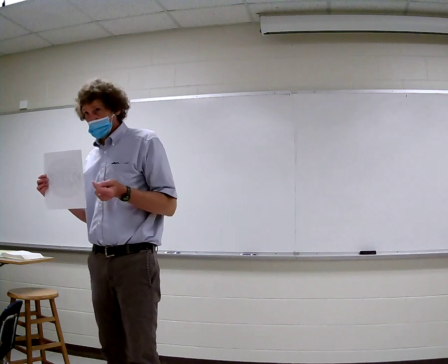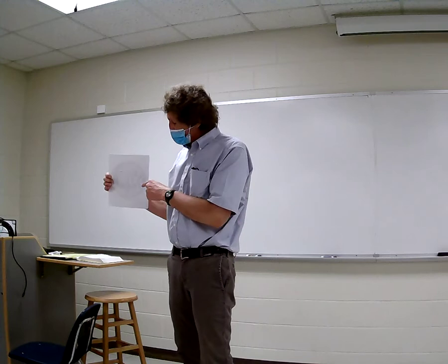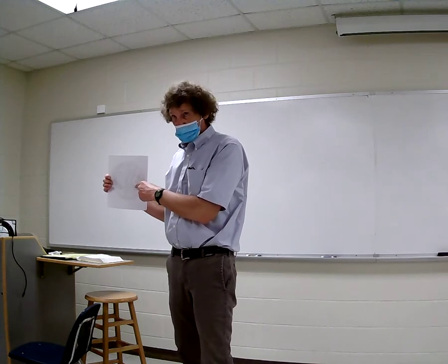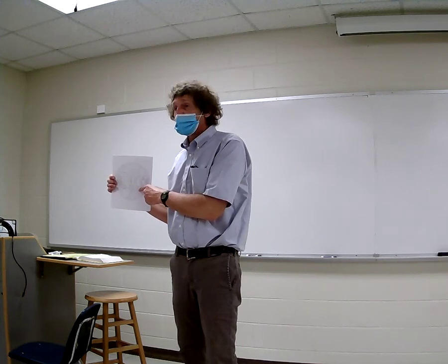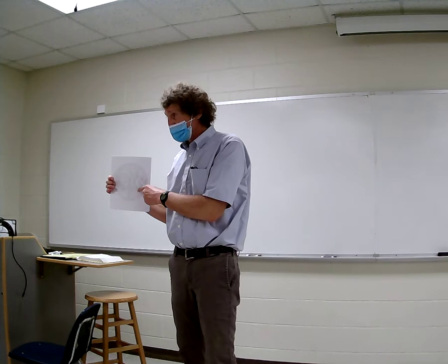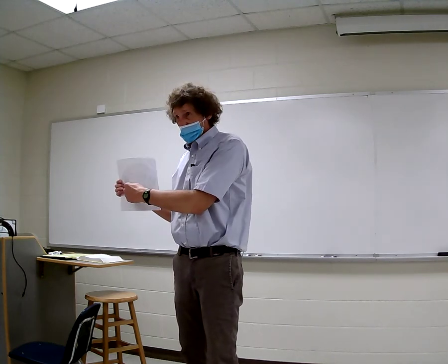Impedance, you have to plot it. It's normalized, right? Normalized load impedance. And it can fall inside the one circle, and if it does, if it's inside the one circle, anything we add in series, any impedance we add to it, will never put it on the rim of the one circle. So we go to the admittance domain.